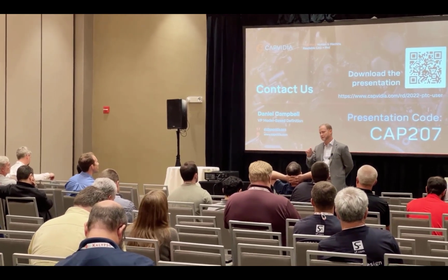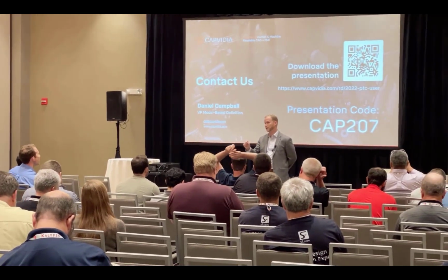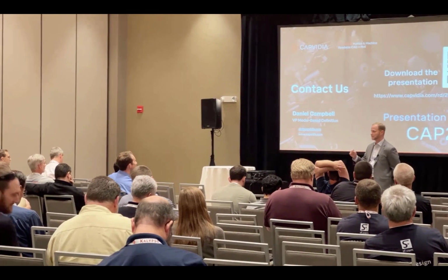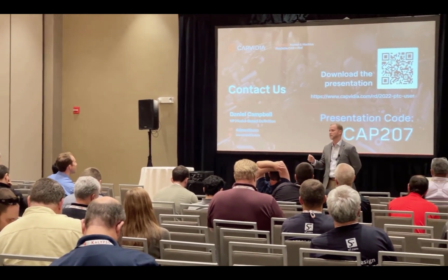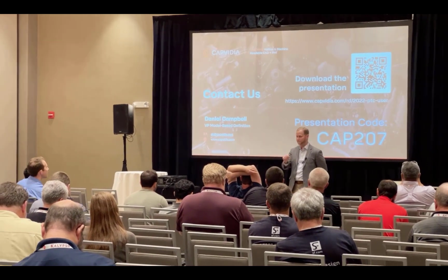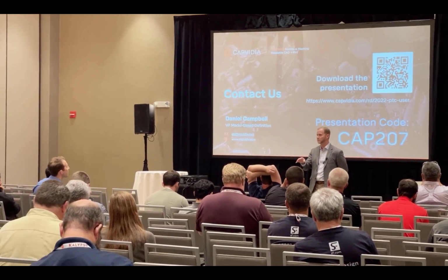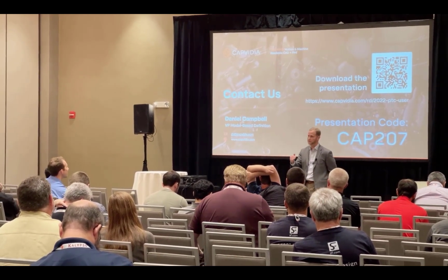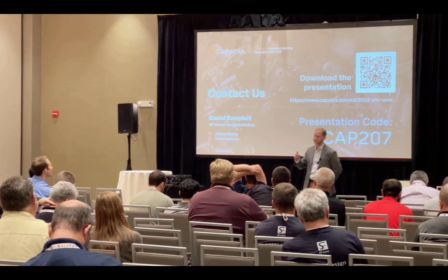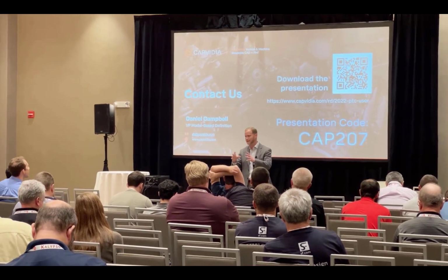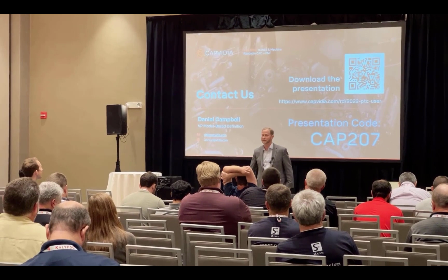So the way that it was done is that we were placing PMI on the model that was associated to certain surfaces. Since there is no standard for visual inspection like Y14.5 or something, we started defining conventions for how to specify that with notes, and then actually parameter data underneath the notes. That contained a lot of the information they needed in terms of knowing what type of inspection to do, because there are various different types of inspections they could do with their camera tool.